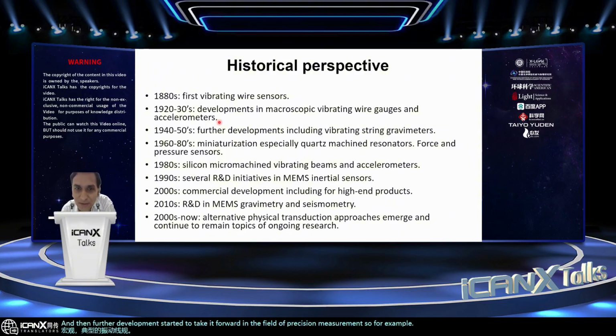So for example, gravimetry, with the first instruments being reported in publications in the 1940s. We then see the advent of MEMS technology, but that's, again, part of the drive to miniaturization. And around that time, you also see a lot of work in quartz crystal technologies. This continues as an evolution of the vibrating string gauges. In fact, vibrating string instruments continue to be used today. But you see work on quartz crystals emerging and then maturing for applications, for example, in force and pressure sensors.